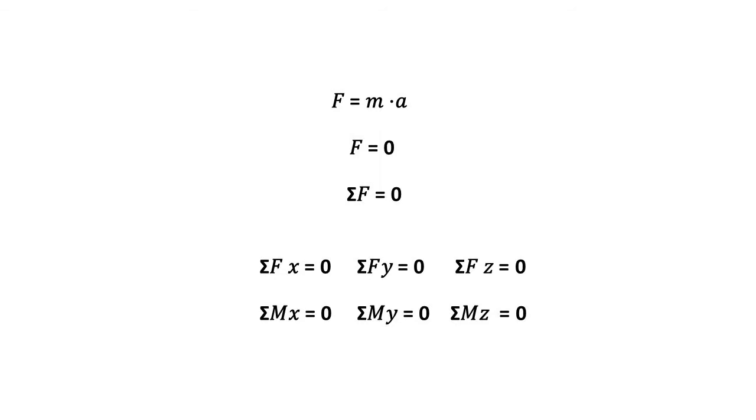So, the sum of all forces and moments: it should make intuitive sense that if an object at rest is subjected to two equal and opposite forces, then it will not move. Similarly, if a steering wheel of a car is pulled with equal force in two directions, it will not rotate. These are just special cases of Newton's second law. The full version of the law is that force is equal to mass times acceleration. As you might expect, in the case of statics, there is no movement and thus no acceleration. Therefore, force would be 0.